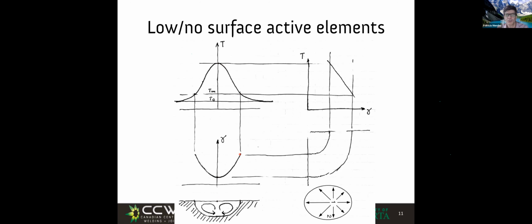That was speculated too, but in this Rocky Flats case, the problem was not arc blow. So look at this. Now, because we understand the temperature distribution, and we just discussed the relationship between surface tension and temperature, I combine both, and I would see that here at the center, I have low surface tension. Here at the edge, I have high surface tension.